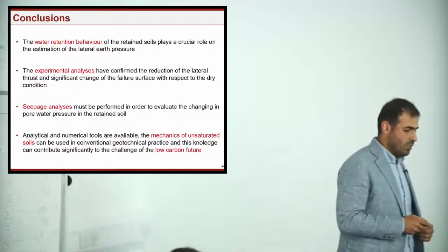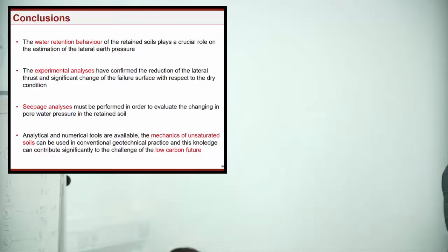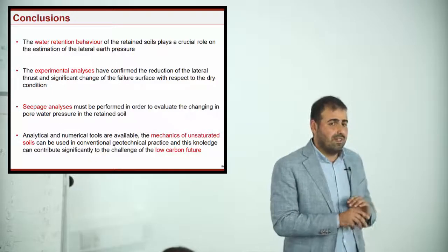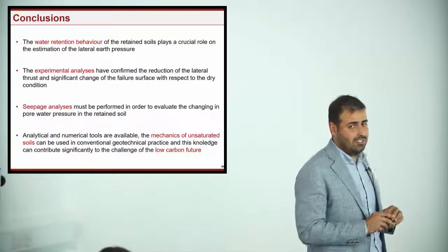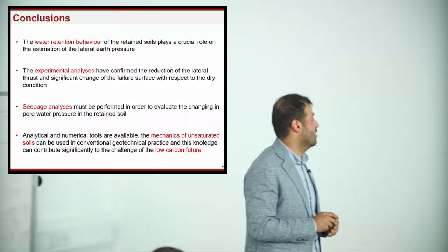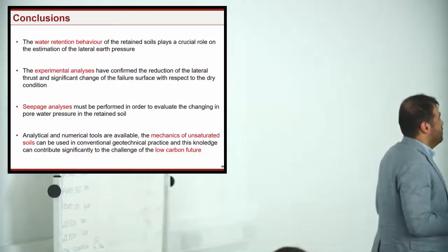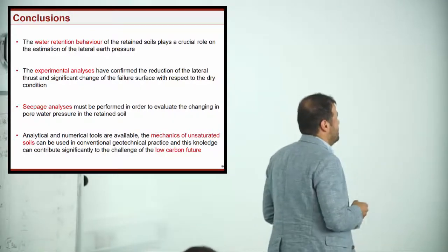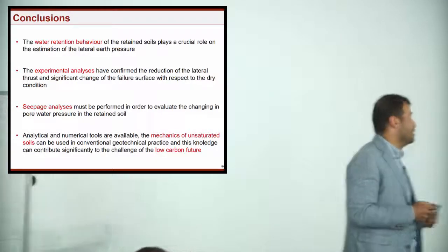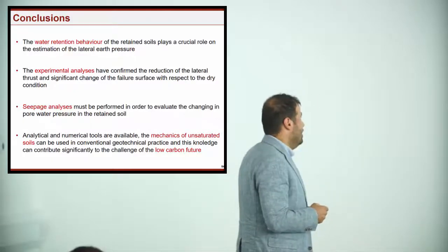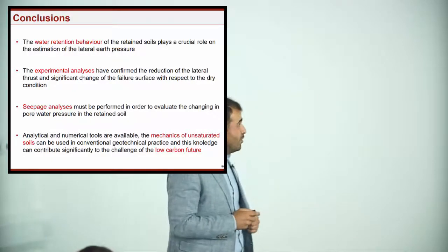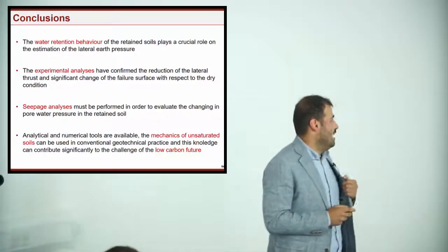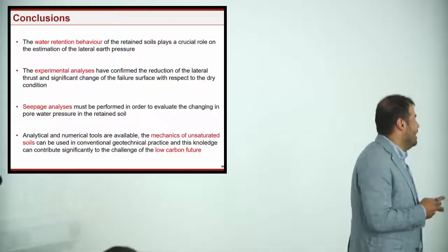As the main conclusion, I would like to say that the water retention behavior and its characterization play a crucial role when we are using the mechanics of unsaturated soils in classical geotechnical problems. The experimental analysis has confirmed the reduction of the lateral thrust and the significant change of the failure surface with respect to the dry condition. Seepage analysis must be performed in order to evaluate the change in pore water pressure in the retained soils. And we have analytical and numerical tools.